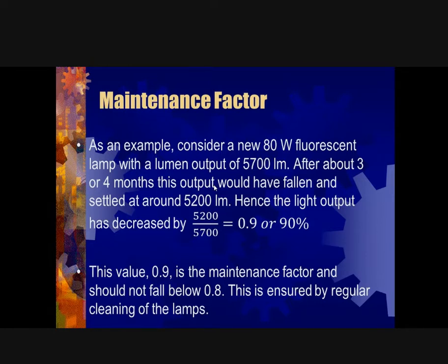That's one factor to consider. Another factor is your paint, the reflectiveness of your surface and all of that. However, after a period of time, remember you didn't put any extra light. After a period of time, our maintenance factor now falls to 70%.